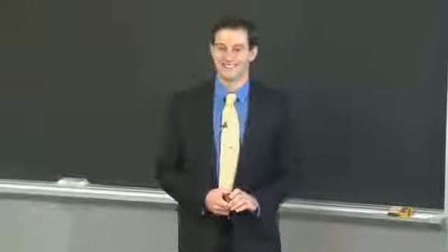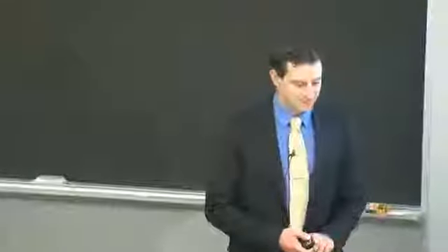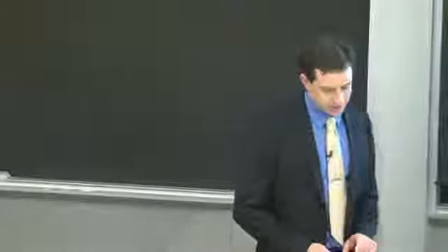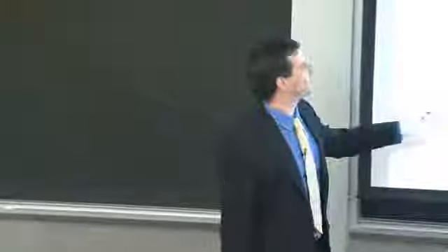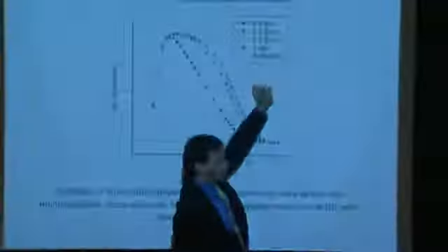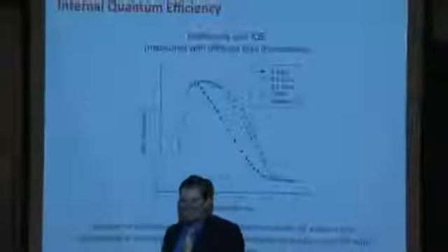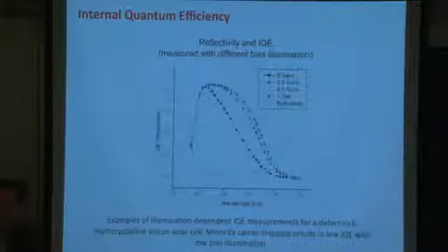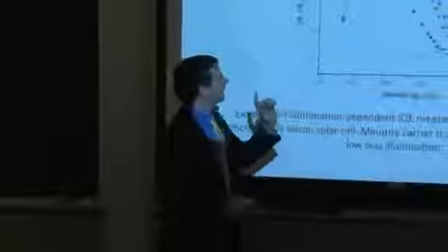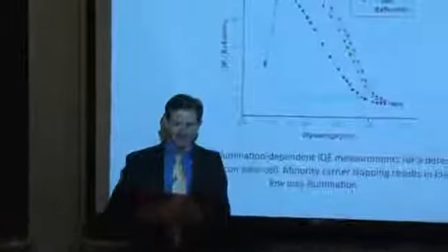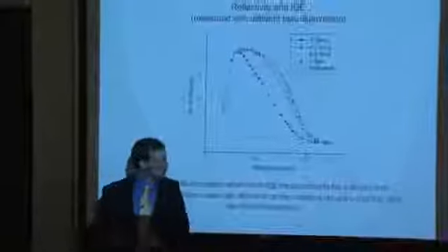How do you have a QE curve for 0 suns? I noticed on your graph, is that kind of extrapolated? Yeah. So this is the bias condition. The bias lighting condition, not the bias voltage as in battery, but bias lighting as in I shine a polychromatic light source at my material. I believe in that case it was a halogen lamp with a series of filters to simulate the solar spectrum.